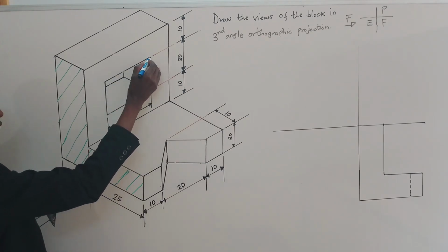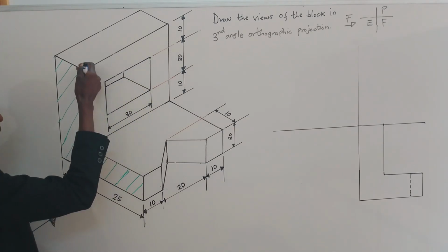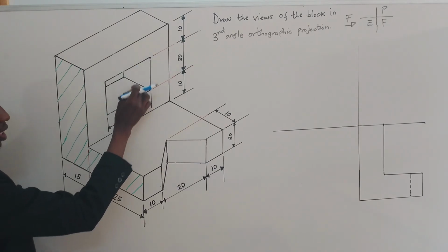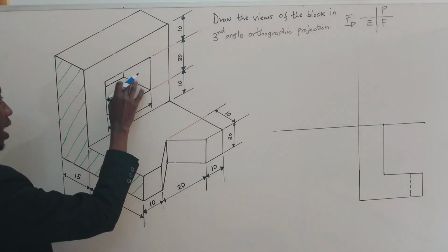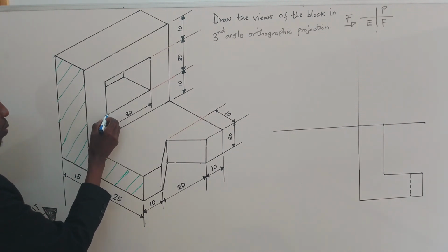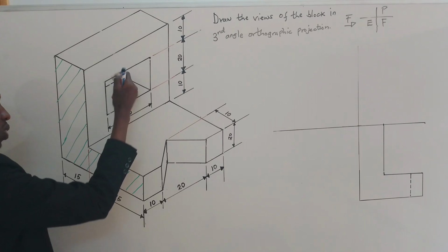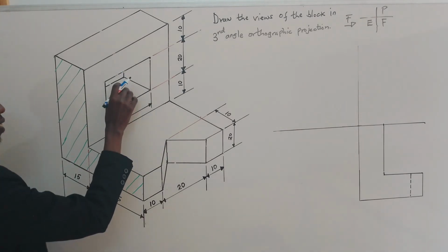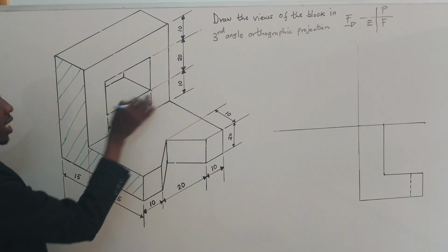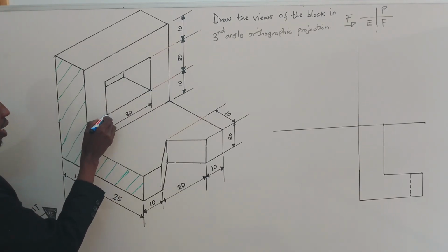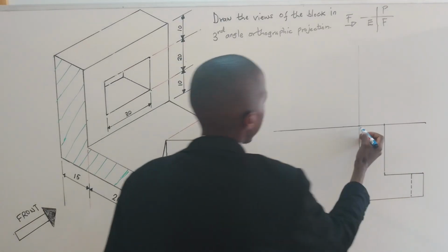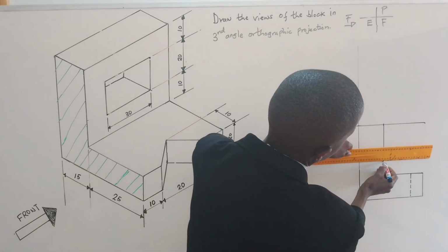So it means again we are not seeing a line going that way. We are not seeing this line going this way. So remember we have this corner and we said we have a corner line. So when two faces meet, this face and this face, it makes a corner line. Now this is outlines, but we are not able to see on this front elevation. So we have this line going that way, then we have this line going this way. Now this one is visible on our board, but not on this side. Now I will pick this one, and this line and this line is on the same eyesight, so it's just one line. So the height from top, from here up to here is 10 plus 20. So I will mark here 30. So 30 is here. Then I will do a broken line.